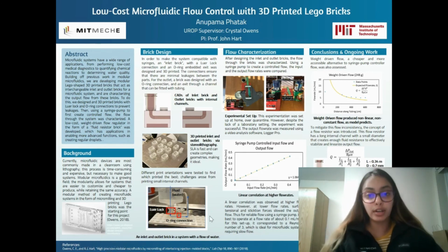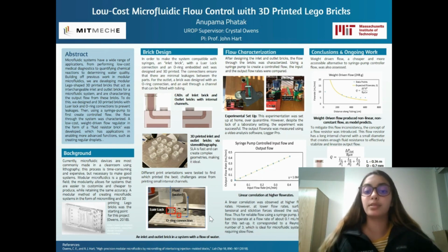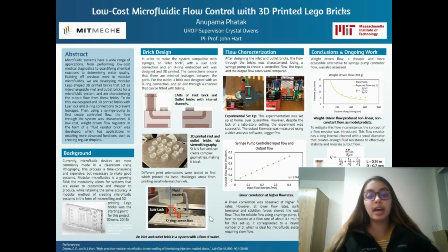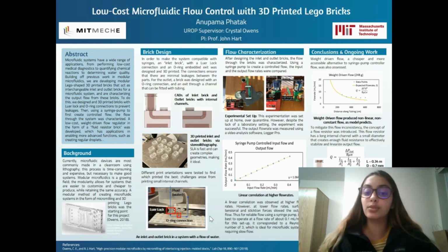Next, I moved on to flow characterization. So what I did was I set up a syringe pump and measured the input flow and the resulting output flow. And what I found was that at flow rates generally used by microfluidic systems, the relationship is linear.